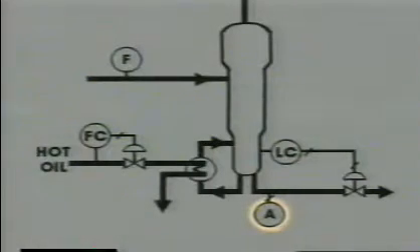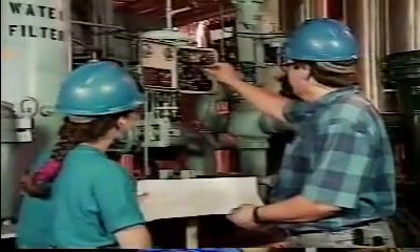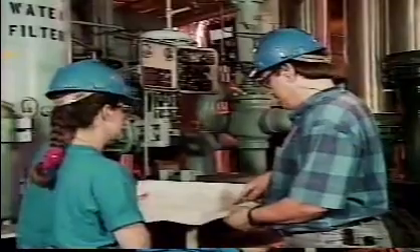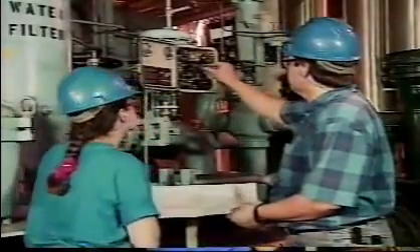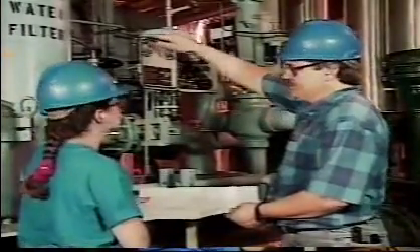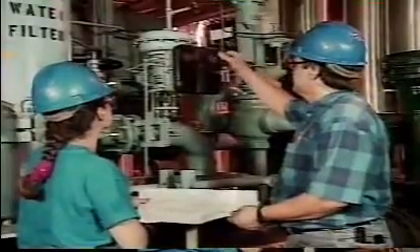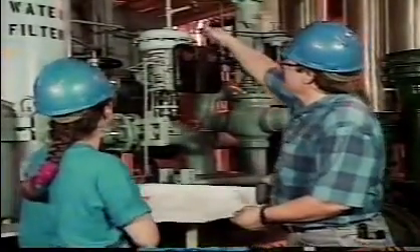This balloon, labeled A, indicates that the process fluid is analyzed as it exits the column. So from a simplified diagram, you can determine the basic operation of the system by identifying the points of measurement and control and the direction of the process flow.